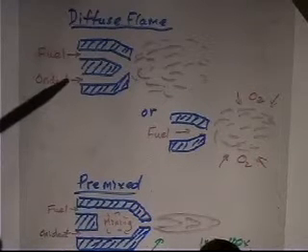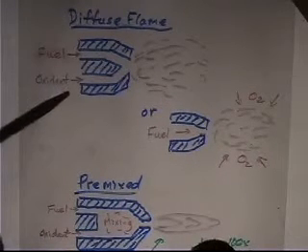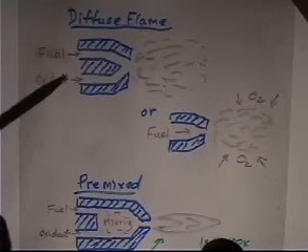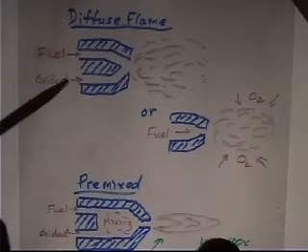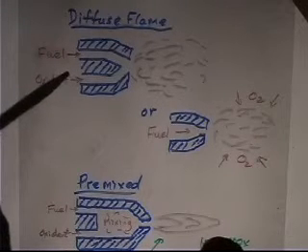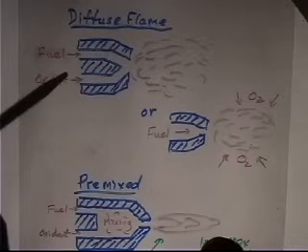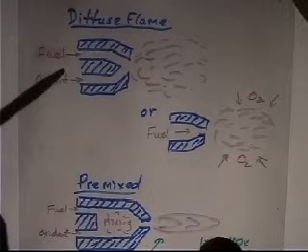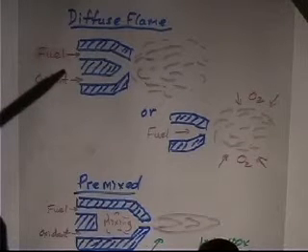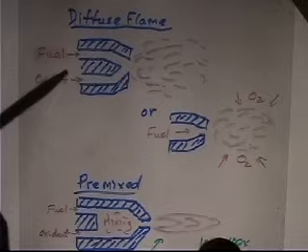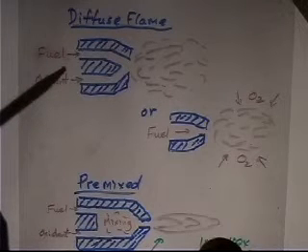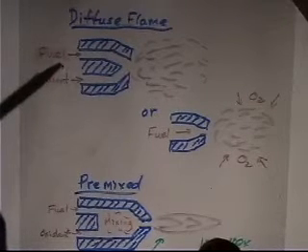So there are flammability ranges of things, and you can look these up in a typical gas handbook. Now, when you look it up, be careful. Flammability ranges are usually at 1 atmosphere pressure and at room temperature, and on a sunny day when someone just sold a hot dog outside on the street corner.